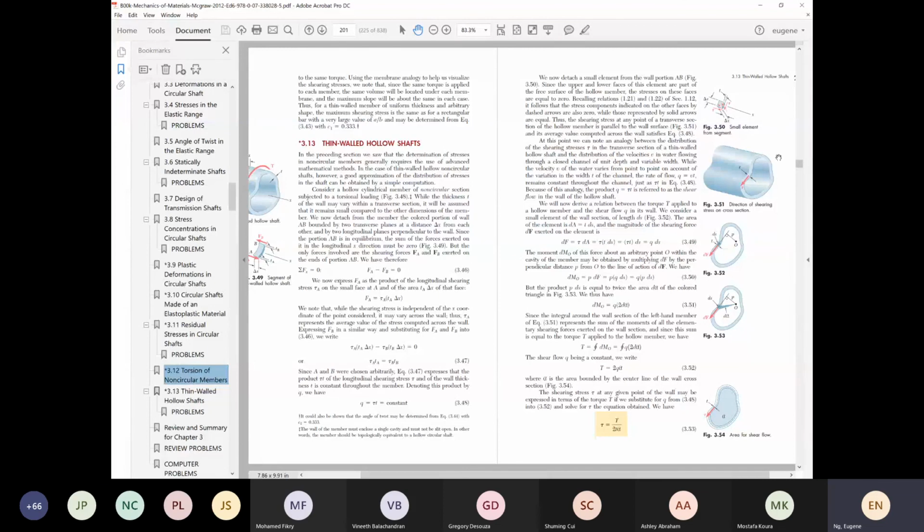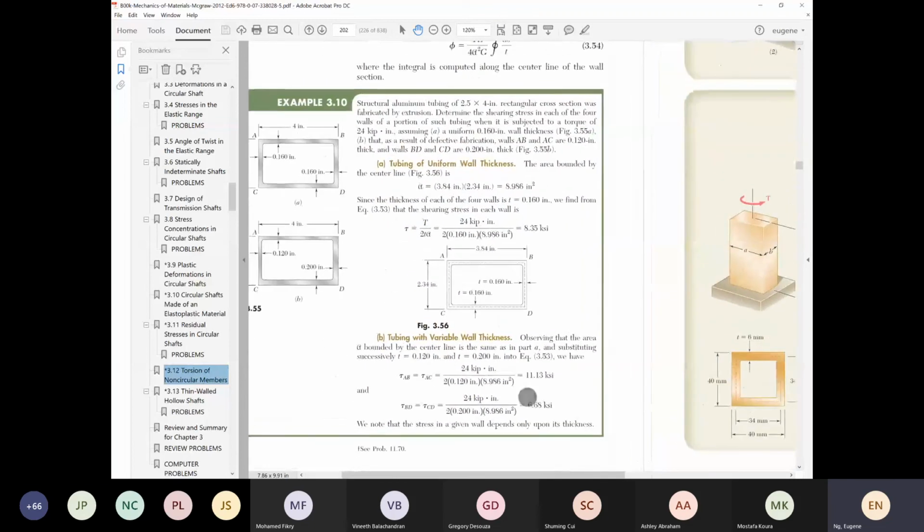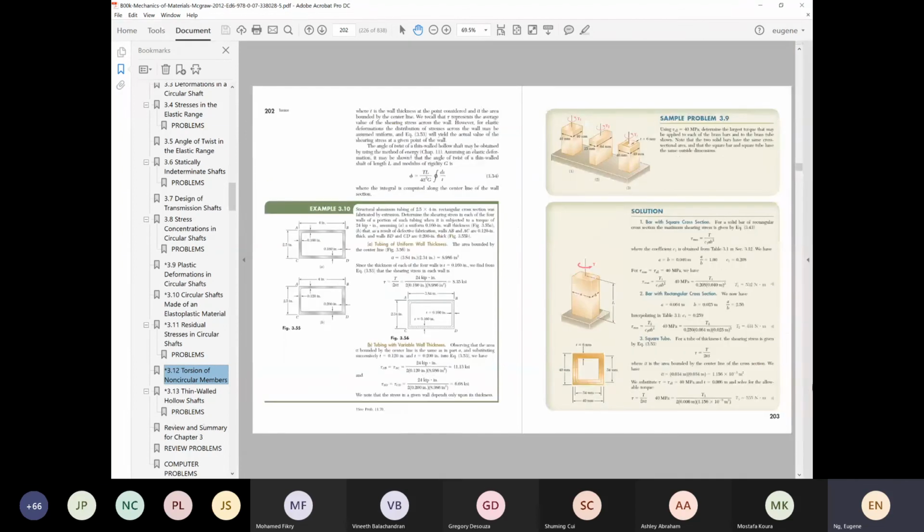As I said, it's basically using a shape function. You have a square section, and you have thin wall analysis also. So you can use this sort of formulas also. But the thing about this sort of formula, the structure has to be a closed circuit. You get what I mean by closed circuit? It cannot have an open channel. I don't think over here they will have anything open channel.